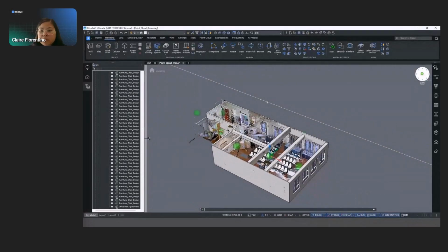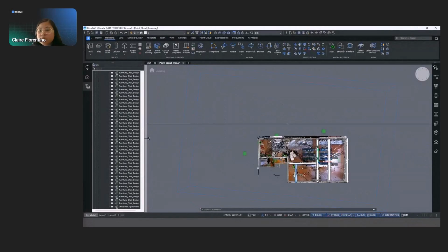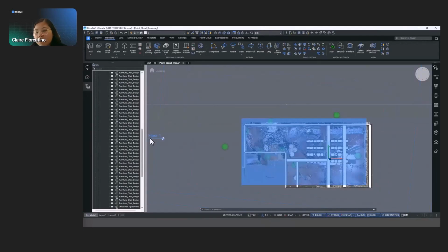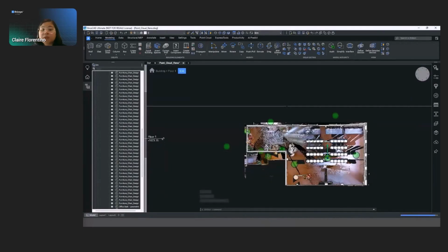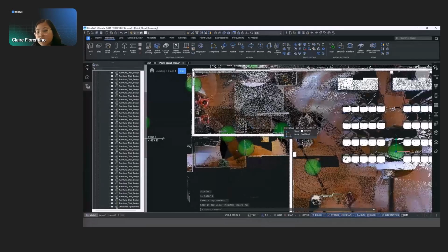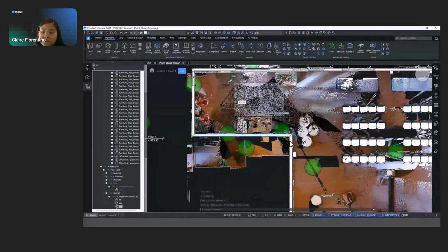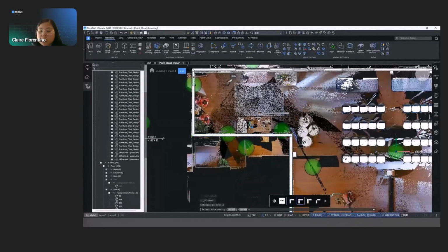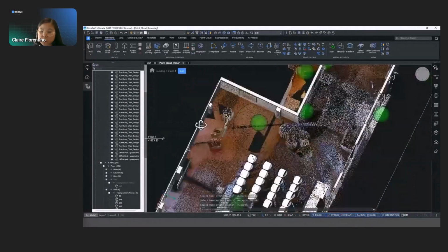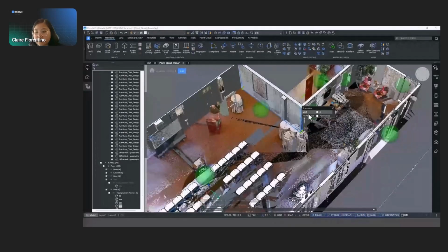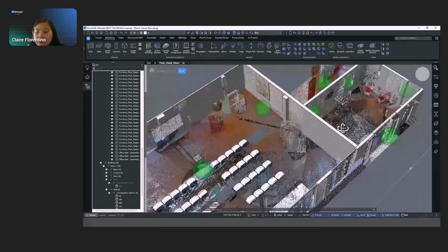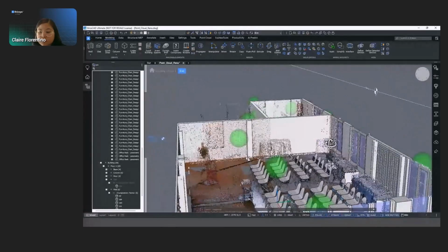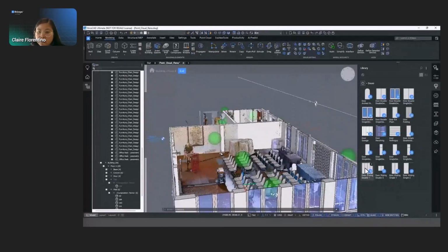if you remember, one of the other things that we needed to do in this space was to create a small meeting room, and that's going to be on this side of the building. Right, a smaller one. So we want to close off this area, and that's quite easy to do with BricsCAD as well. You can just change the wall connection and extend the wall quite easily in just one click. That's going to be extended to the nearest wall. So we have this new room.